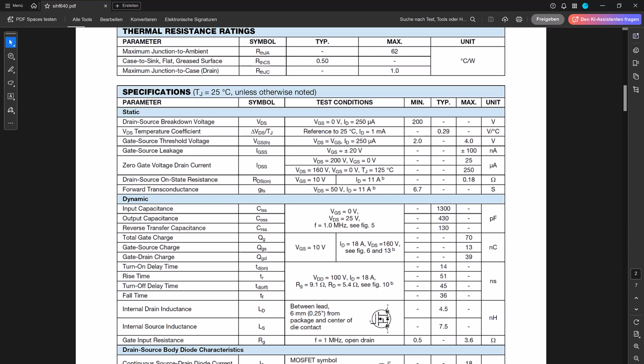Gate shorted to source and a tiny leakage current. It is not the voltage at which the transistor works. It's the voltage at which, when you inject a small leakage current, the voltage stabilizes. A precise definition, and it explains why a round number like 200 volts needs half a page of footnotes.